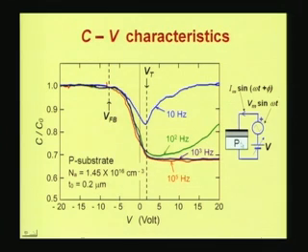Now, how do you know that there is a capacitance here between these two in terms of the terminal characteristics? Well, when you apply a small signal voltage, there is a small signal current that results in the circuit. The relation between the small signal current or the sinusoidal current and the sinusoidal voltage tells you whether the structure is resistive or capacitive.